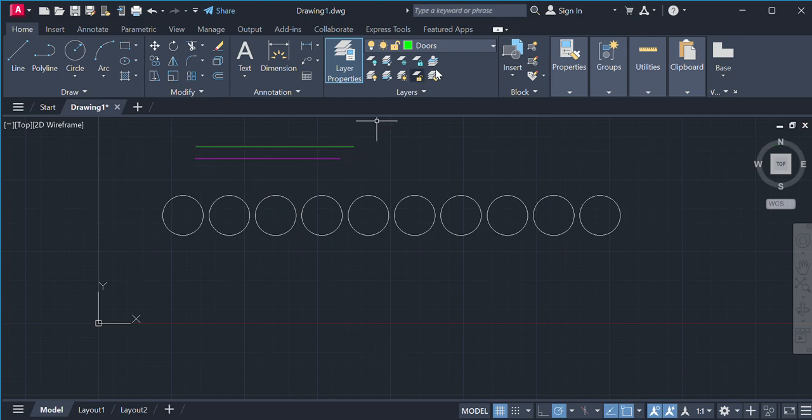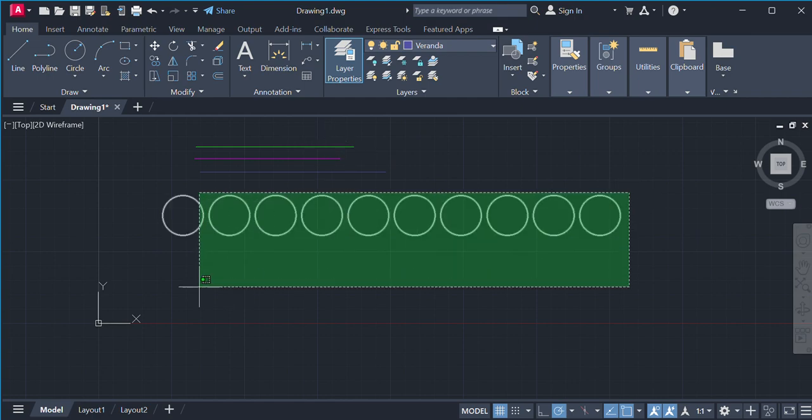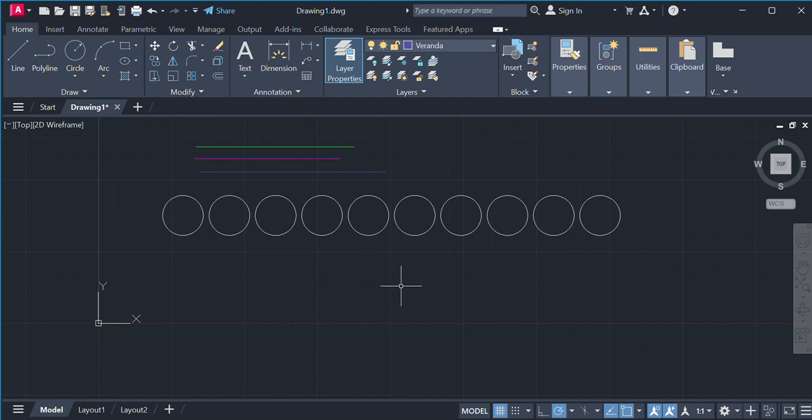It takes like 2 seconds. It looks like it's taking up time, but it takes like 2 seconds. Then let's assume you've drawn lines from all the layers, and then you've drawn your entire house plan, but you realize everything is under layer 0, which is not the layer you're trying to work with.